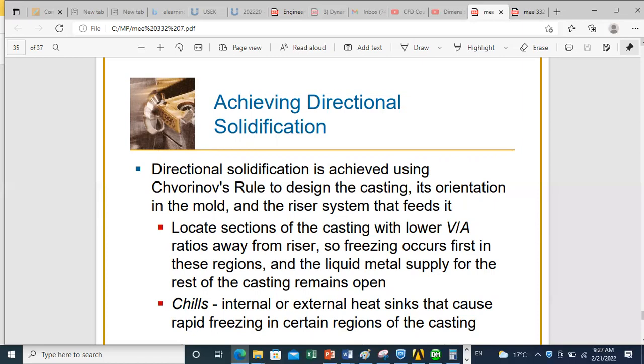So you should study for each part what the solidification time is. According to this, you will design risers, and you will put risers in zones close to the critical zones characterized by small solidification time, because in this way the riser will ensure continuous supply to these zones and will prevent blocking effects, because some other zones can solidify before. So you should still be able to reach these zones by supplying molten metal to them.